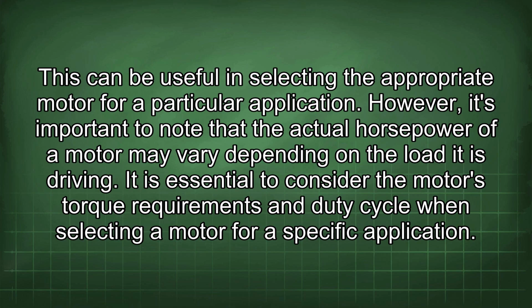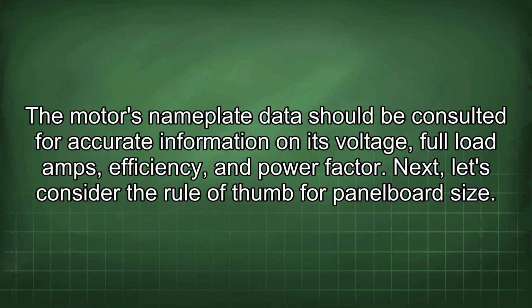However, it's important to note that the actual horsepower of a motor may vary depending on the load it is driving. It is essential to consider the motor's torque requirements and duty cycle when selecting a motor for a specific application. The motor's nameplate data should be consulted for accurate information on its voltage, full load amps, efficiency, and power factor.